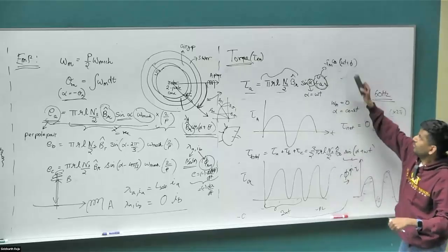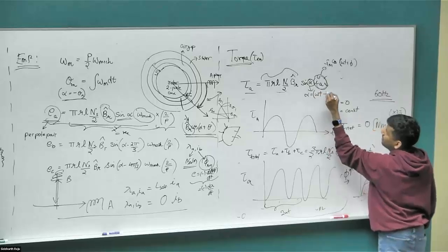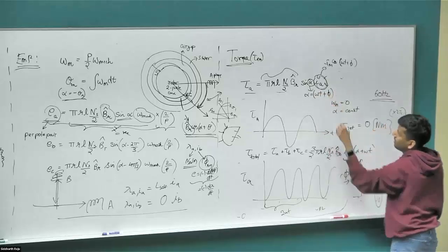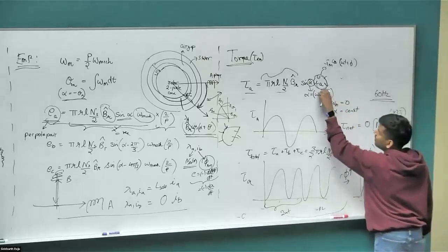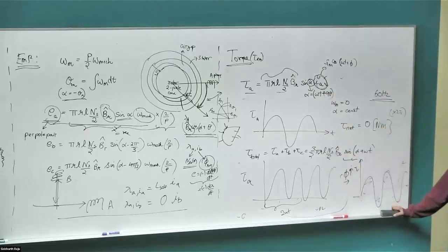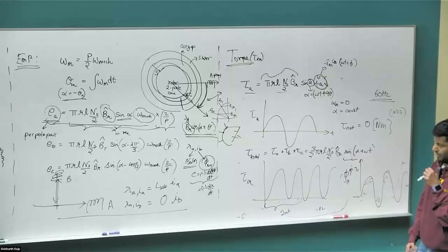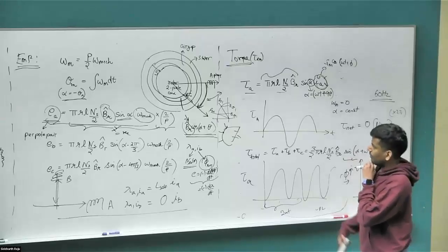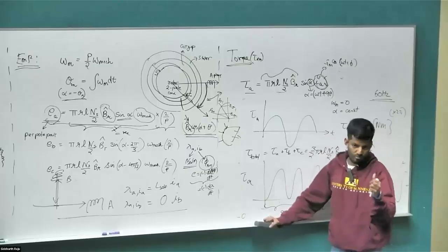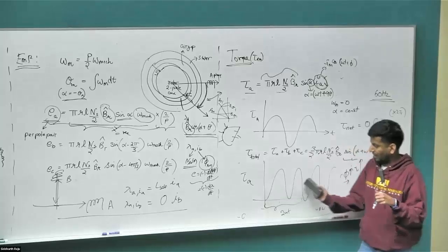So for the maximum torque to be achieved in both the cases, you would have to have alpha equal to omega t plus 90 degrees. That will end up giving you the cos omega t component. Right? So it needs to be phase shifted by 90 degrees so that you can get the maximum torque. In other cases, you will get non-maximum torque. So once you get a one-phase permanent magnet synchronous motor rotating, you can continue producing torque because there is a net average torque.